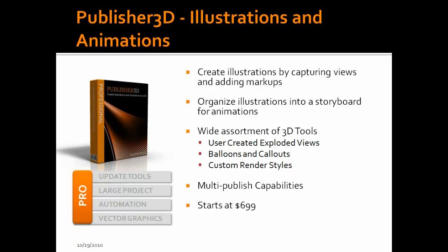So here's the basics of the product we're going to cover today, and then we'll jump straight into a demonstration of this product. Like I said, the whole goal of using this product is to create and capture views of your 3D model. Then you can add markups and balloons to each of those views. And each of those views, which we call illustrations, are organized into a storyboard. The storyboard has a couple of uses. One is just organizing a set of illustrations that you're going to publish, or grouping them. And the second is to create an animation or a timeline for that animation. We'll go through both of those activities of using the storyboard.